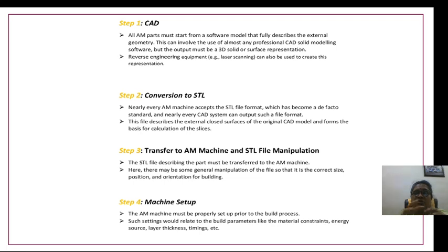Like that, here we develop triangular shapes and can locate the spatial location. That is the de facto standard, and nearly every CAD system can output such a file format, which describes the external closed surfaces of the original CAD model and forms the basis for calculation of the slices.